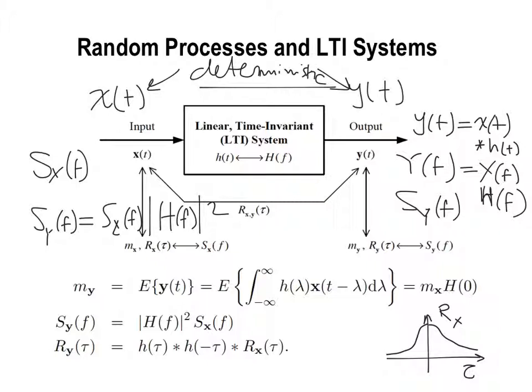Okay. Similarly, now I ended up representing my random process, which is x of t. The input random process x of t, instead of being deterministic, is random. But in the second order, if I represent it by R in the time domain, which becomes Sx in the frequency domain, I still have a power spectral density of the input.